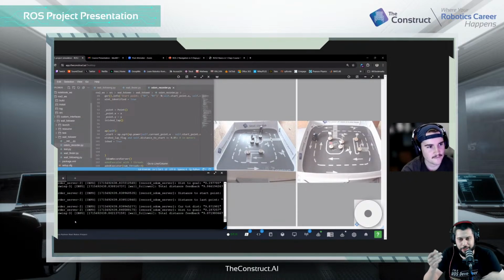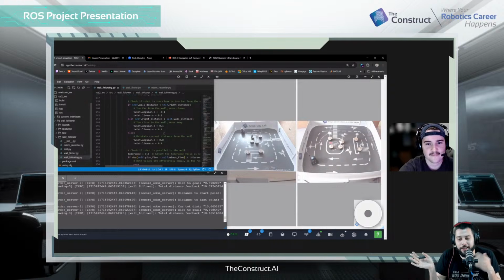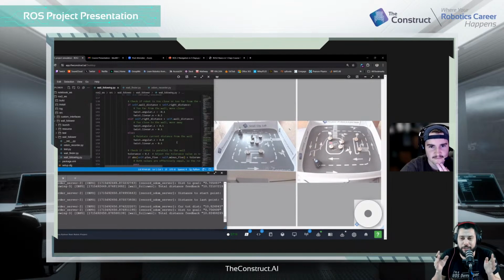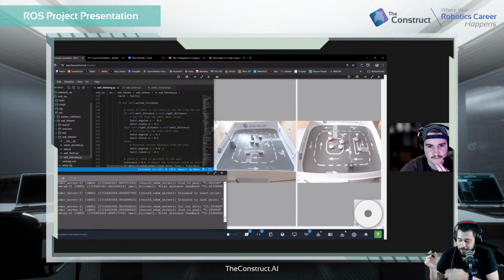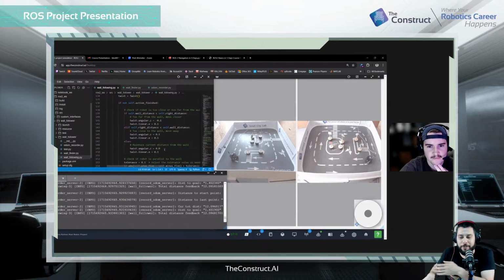for when there's a hard corner. But you could actually get rid of the looking at the right and the front, the if-else, to do that movement, and just look at the error, the difference between those values, right? So you were saying a little bit above the right side, a little bit below, and you can actually do what I said about a PD.